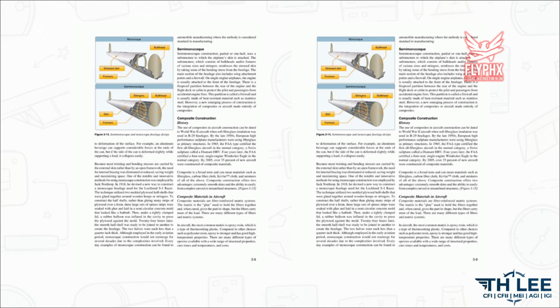construction. If you look closely at how these are built, you'll see a complex substructure attached directly to the inside of the airplane's skin. We have bulkheads, formers of various sizes, and longitudinal stringers. These reinforce that stressed skin by taking a significant portion of the bending stress, totally preventing that beverage can deformation.